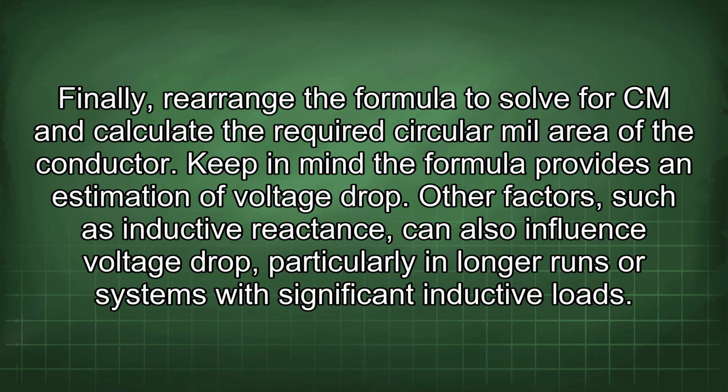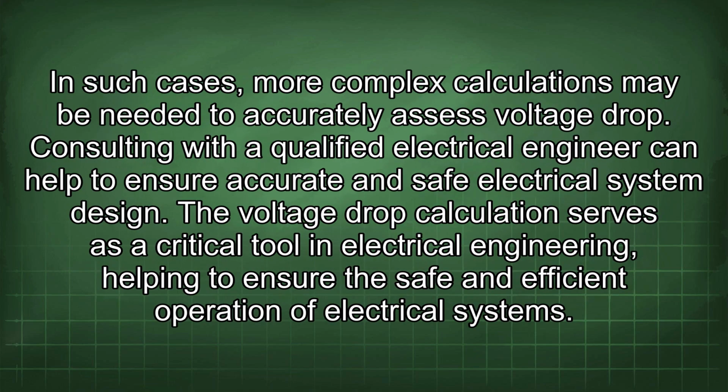Keep in mind the formula provides an estimation of voltage drop. Other factors, such as inductive reactance, can also influence voltage drop, particularly in longer runs of systems with significant inductive loads. In such cases, more complex calculations may be needed to accurately assess voltage drop. Consulting with a qualified electrical engineer can help to ensure accurate and safe electrical system design.